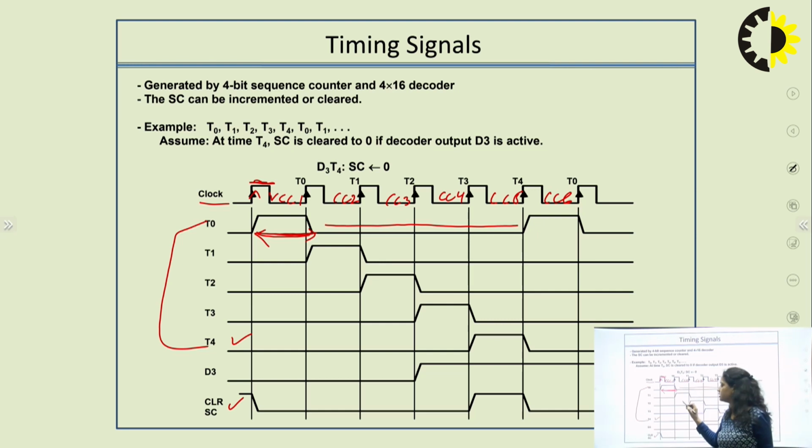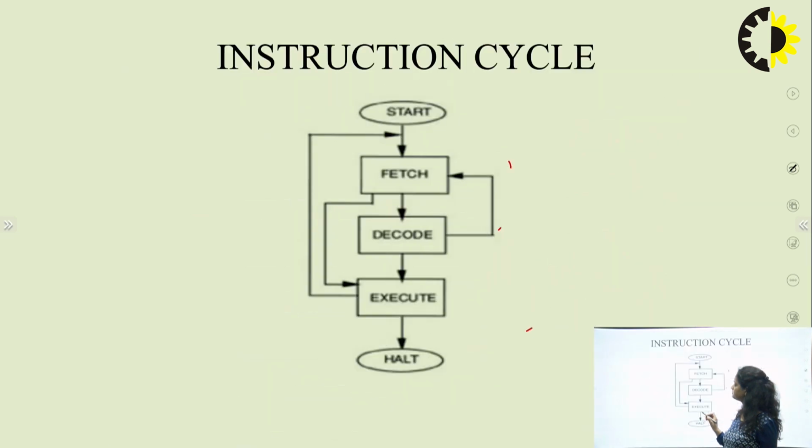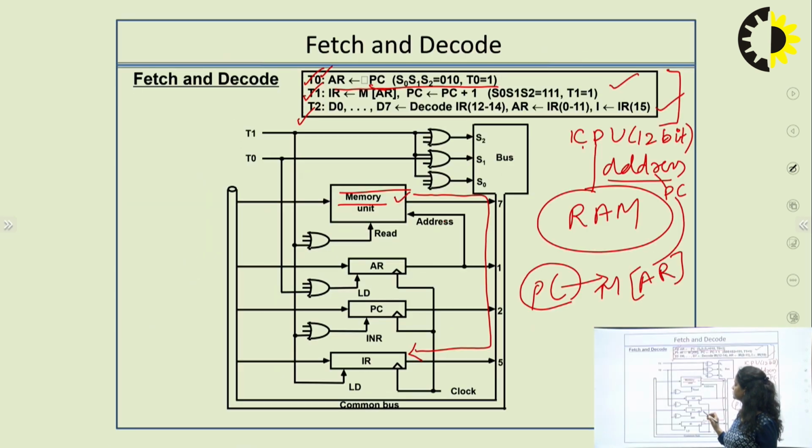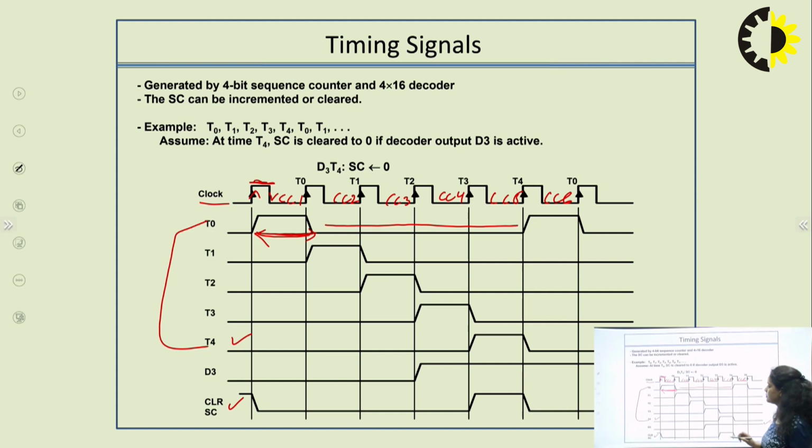Then the next operation is again copying the instruction from memory to the I register and then incrementing the program counter. The 2 operations are performed in timing cycle T1. So this process is shown in timing cycle T1 with a high rising edge of a clock pulse and then stable and then lowered down. So this particular duration is showing clock cycle CC2 and showing that the 2 instructions are executed in a particular time duration, that is in T1.